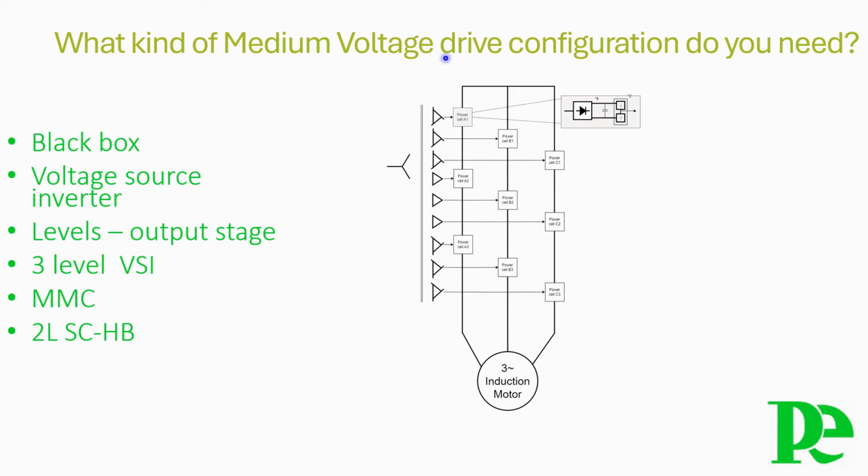The integral dry multi-winding transformer provides for adaptability to available input voltage, clean input power thanks to the cancellation of the harmonics by the phase displacement in the secondaries. Multipulse inputs go from 18 to 54. Isolation from the grid, avoiding potential resonances and reducing impact from utility transients such as lightning and other equipment switching.